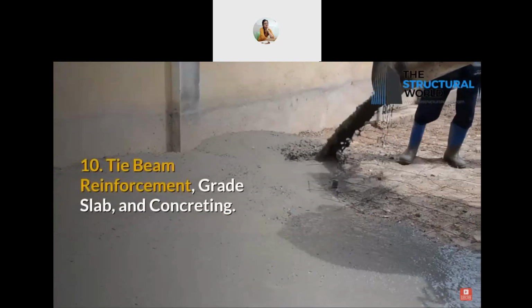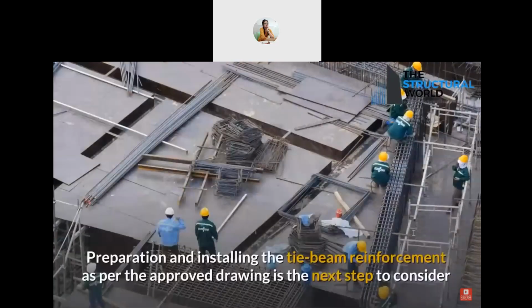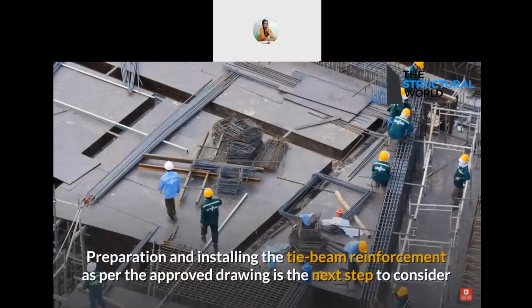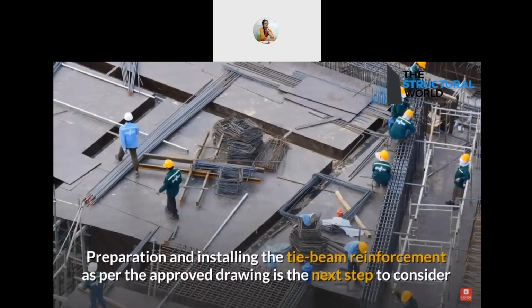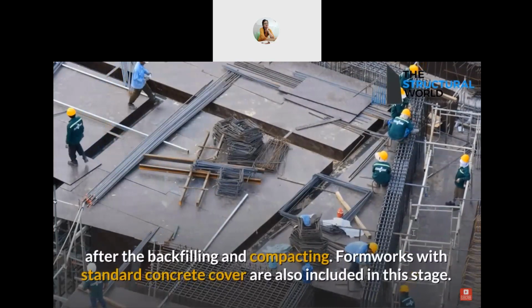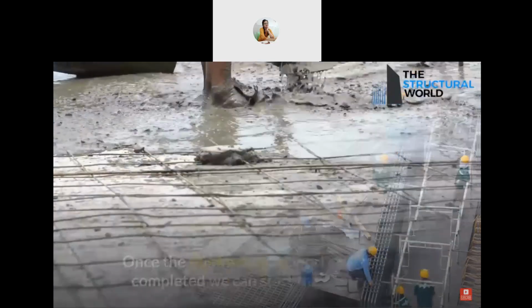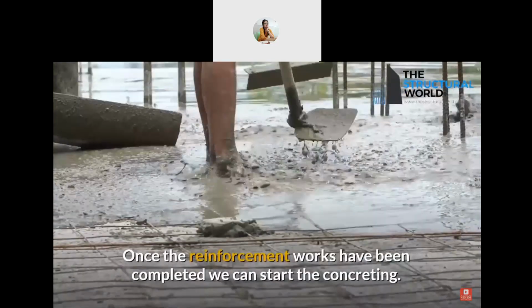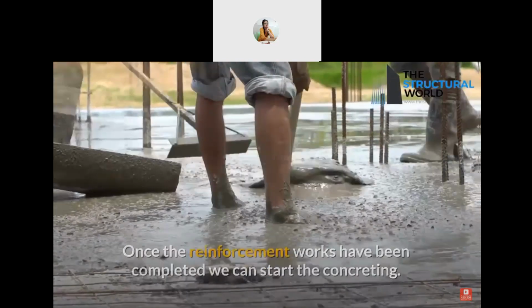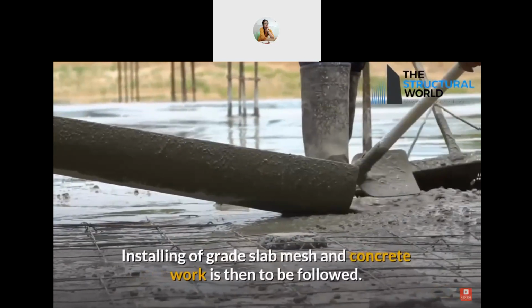10. Tie beam reinforcement, grade slab, and concreting. Preparing and installing the tie beam reinforcement as per the approved drawing is the next step to consider after the backfilling and compacting. Formworks with standard concrete cover are also included in this stage. Once the reinforcement works have been completed, we can start the concreting. Installing the grade slab mesh and concrete work is then to be followed.